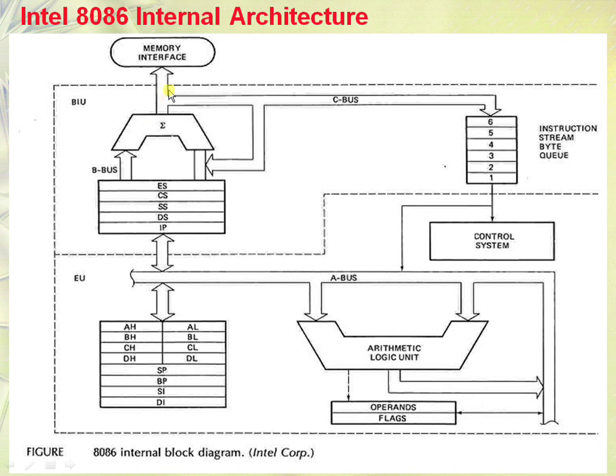Now based on this physical address, the processor is going to fetch the instruction which is provided at that particular address. Now that fetched instruction would be stored inside this instruction byte queue.